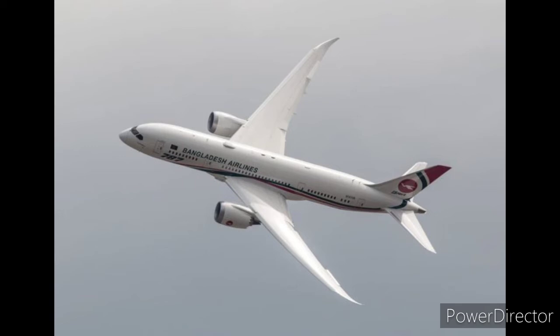Our objective in wing design is that it should reduce the drag, and it should create more lift. That is the objective. So, in order to meet this objective, we have to choose different types of wing according to our needs. If you're flying a supersonic aircraft, you need to go for a delta configuration or a triangular kind of configuration.